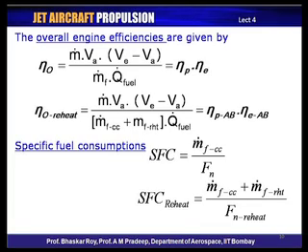If the efficiency of thrust production is not high, and if you desperately need thrust, you have to pump in more fuel to get thrust, in which case it will show up in the SFC definition that is shown over here. So, this SFC definition now shows, which one we have talked about before, that if you just have a combustion chamber in a basic jet engine, SFC is defined in a very simple manner.